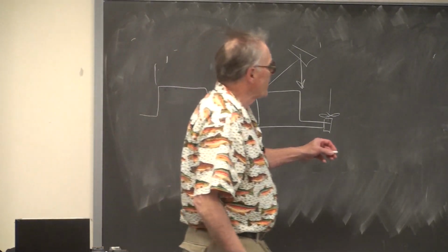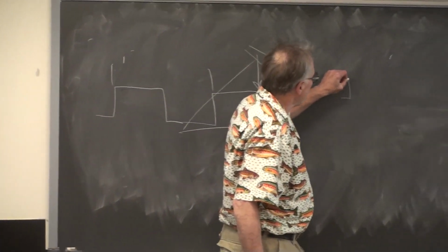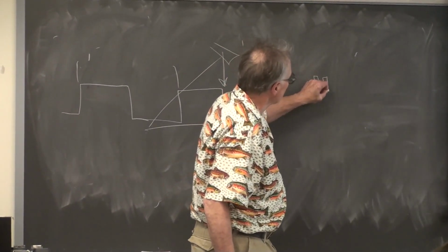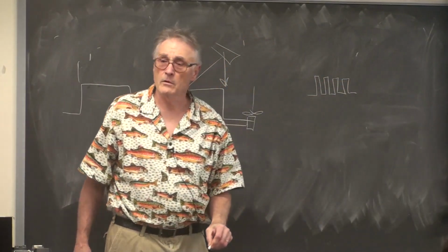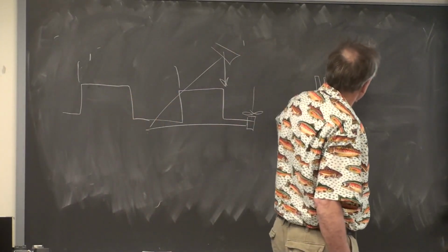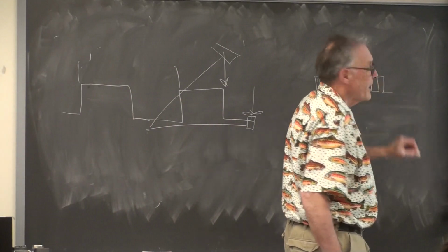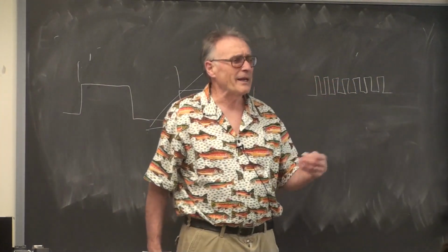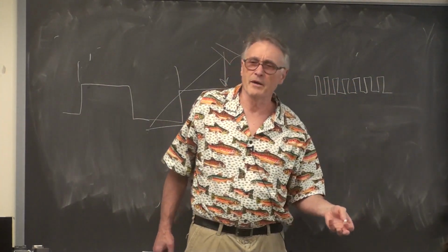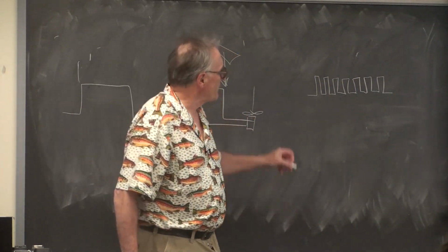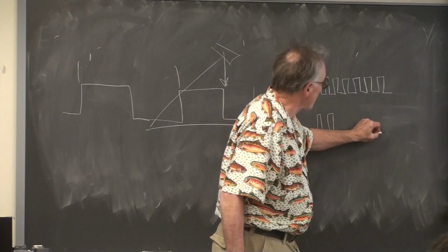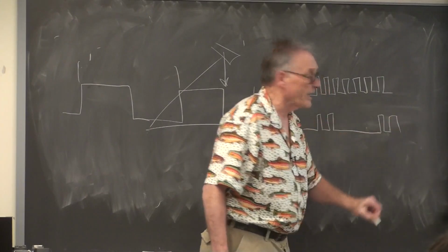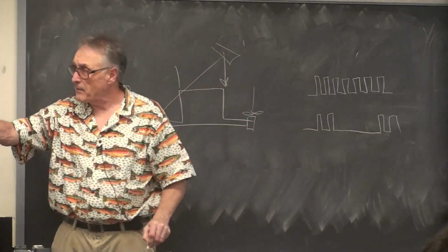So in main, now in your main that is absolutely a null main, you toggle a bit. You toggle a bit just as fast as you can. And it turns out when you do that, it's about 8 megahertz or so. I've tried this. You toggle a bit. When the interrupt fires, the bit stops toggling and then starts toggling again when you're back in main.